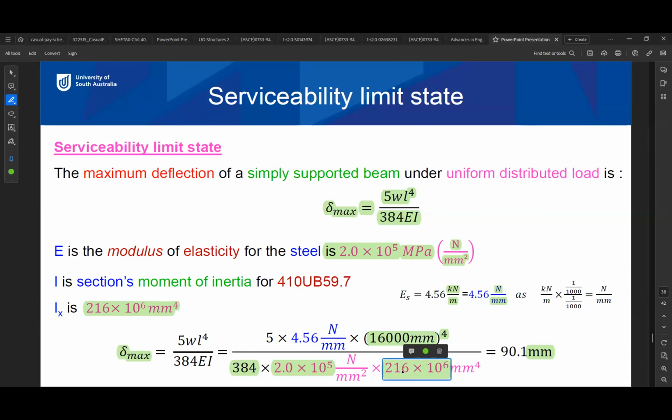You increase the inertia. When you increase the inertia, what happens to the deflection? It decreases, because it is inversely related, right? Just the idea of what we are doing. Everything will stay almost the same except for the I. That I number increases, for the 216.